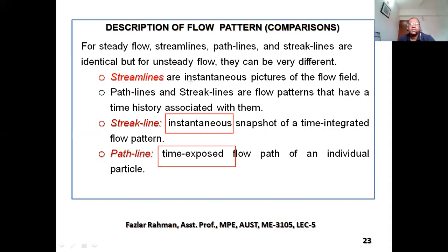Streamlines are an instantaneous picture of the flow field. That means they are based on time. What is the definition of the streamline? At every point you make a tangent, and that tangent will give you the direction of the fluid particle.